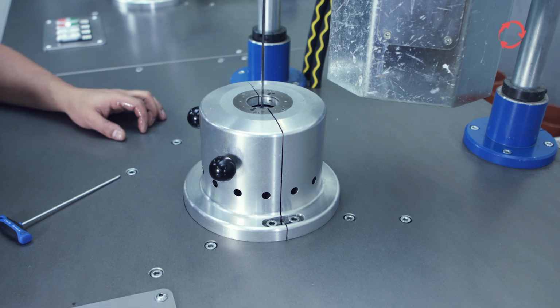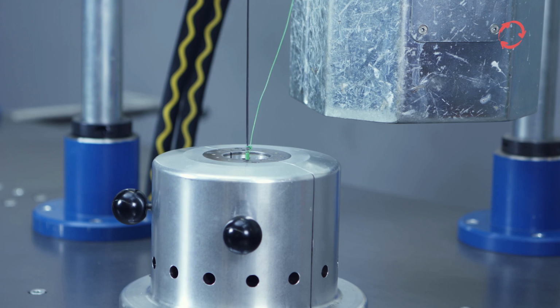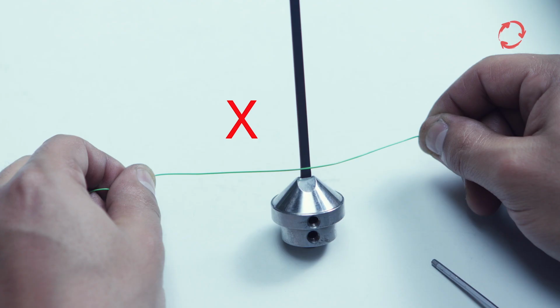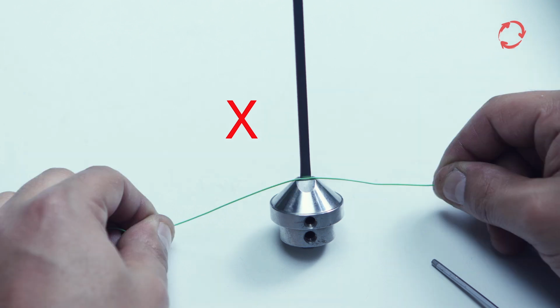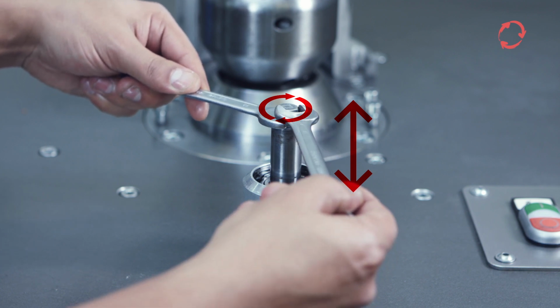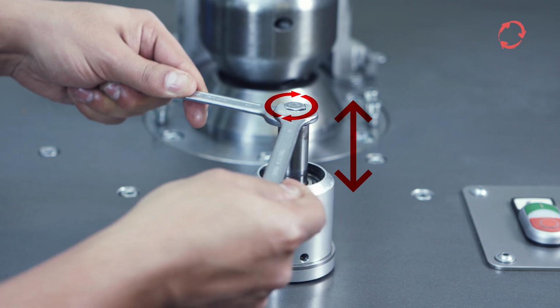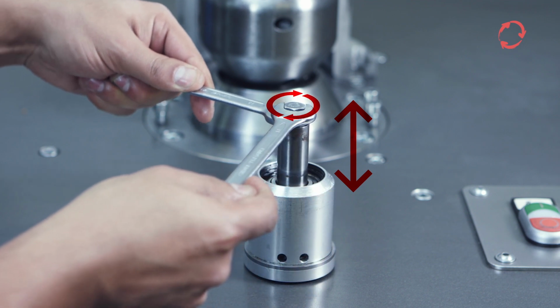Now check the correct adjustment of the intake via a test run. If the winding head is too high, the spiral wire will rub against the magnets during the winding process and tear. If it is too low, the winding point on the mandrel will be incorrect, and the desired dimension of the spiral cannot be reached. If it becomes necessary to correct the height, the intake must again be removed from the winding head, and the height must be readjusted on the adjusting screw.